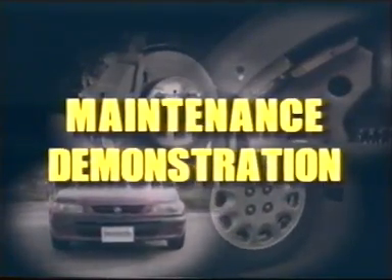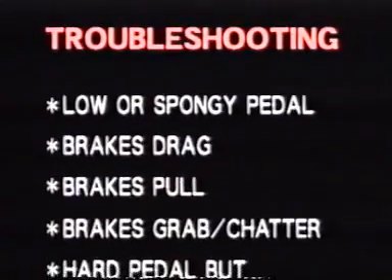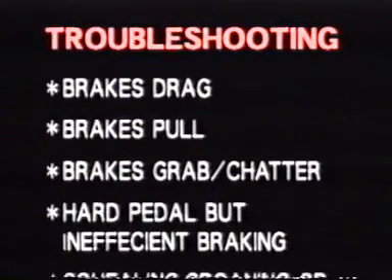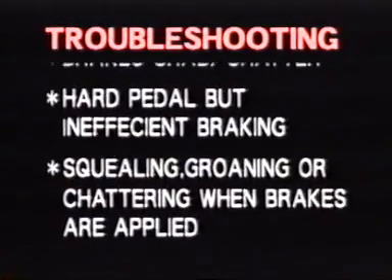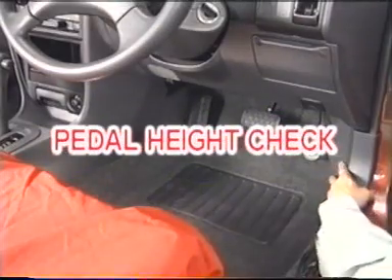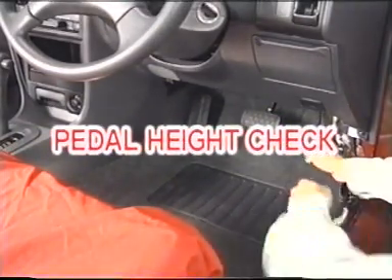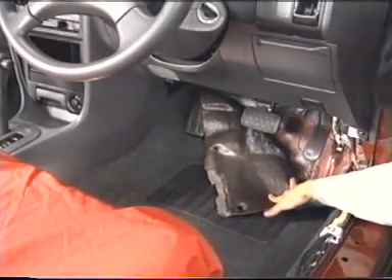These are some examples of the problems observed in the brake system. Here is a lineup of some of the typical problems and troubleshooting for them. Inappropriate brake pedal height or insufficient free play could cause brake drag. Check the height of the pedal.